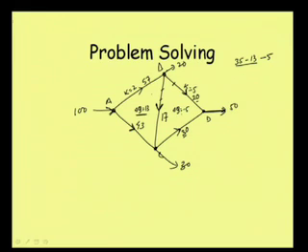So how to check? We again need to check, because the K values are known and are not changing; they are remaining the same. Of course, in this pipe flow problem, if we consider the formula f L V square by 2 g D, or f L Q square, and if we consider the f value to vary with the Reynolds number, then of course our K value can keep on changing.